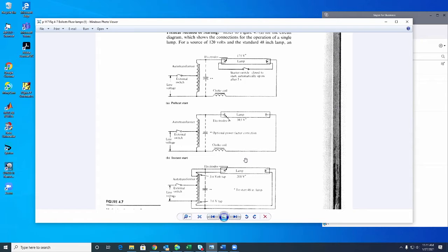So if you heat that gas, as it gets hotter, it conducts electricity more easily, and then there can be a runaway discharge, increasing current, getting hotter, increasing current, because the resistance of the lamp diminishes. So then they put a coil to limit the current. They don't put a resistor because the resistor consumes power. They put a coil which consumes only reactive power, but not watts. Okay.